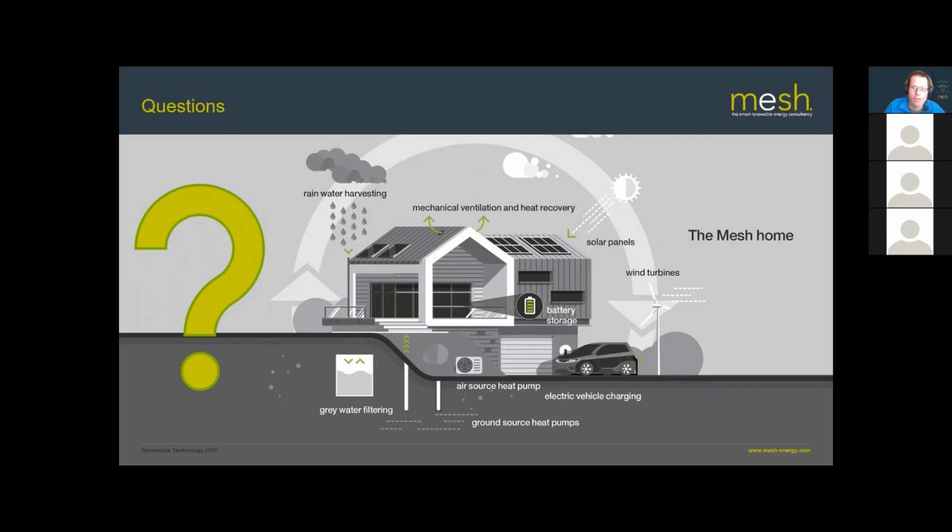How can you tell which inverters and panels are the best? Asked John. That's a good question. Things to look at are lengths of warranties and installer recommendations. Especially on the panels, the linear performance warranty will guarantee a certain output after a certain number of years.